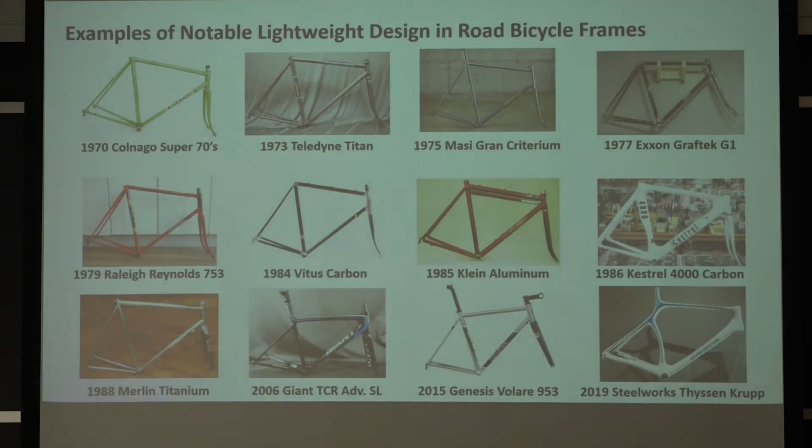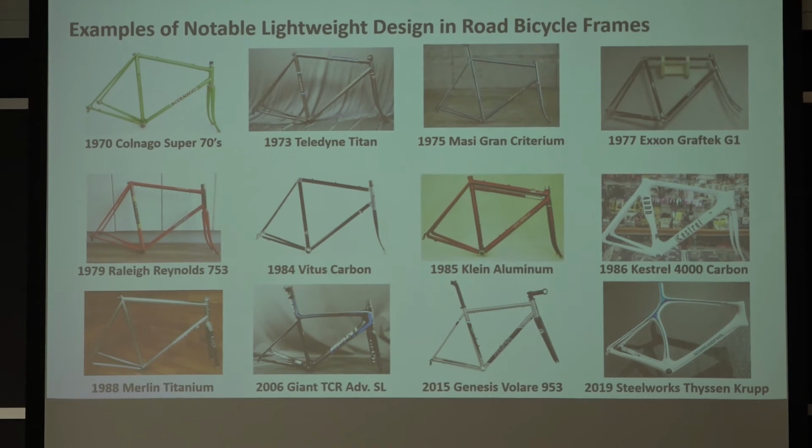The issue is that when you braze these things, you've got to make sure the steel doesn't get too hot, or else you could change the microstructure substantially enough that it wouldn't be as strong anymore. This is why they went to tubes that had thicker cross sections just where they're getting welded, and then they were thin in the middle. Some of the really good manufacturers used silver solder, because the melting temperature is much lower for silver than brass, so you could heat the joint up less and retain more of the strength of the joint.